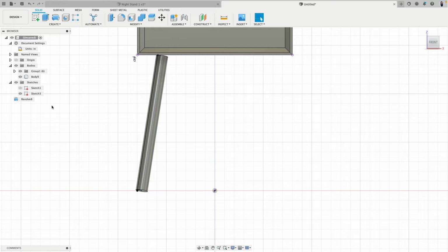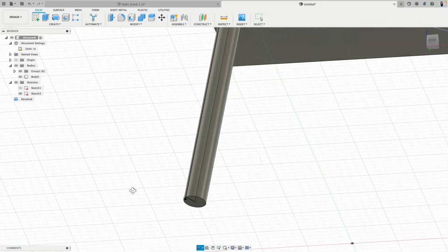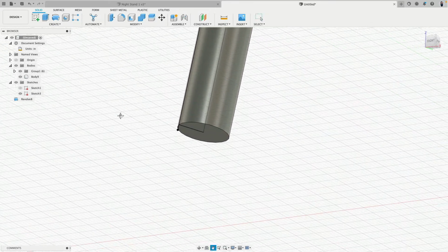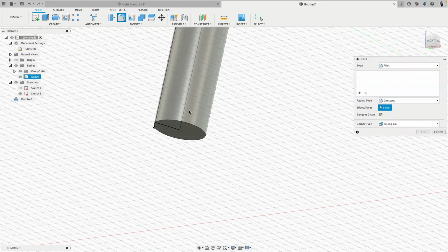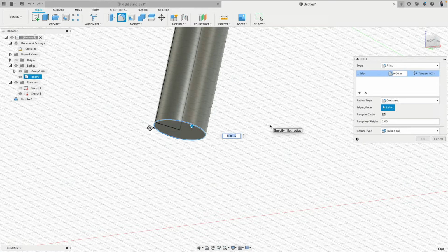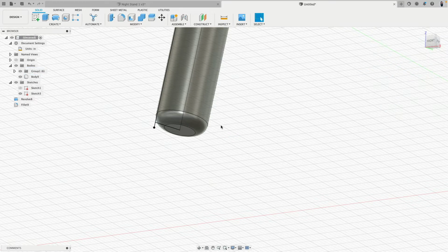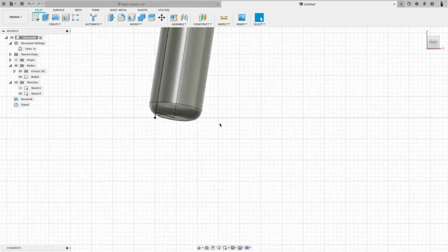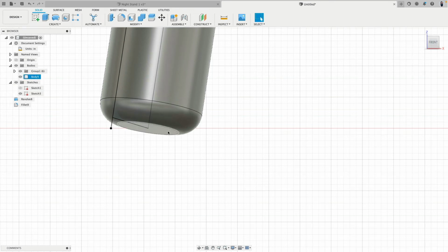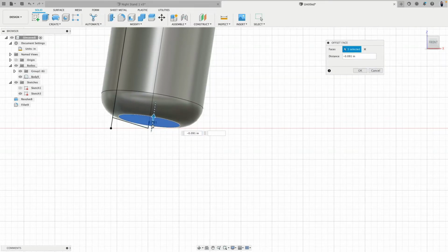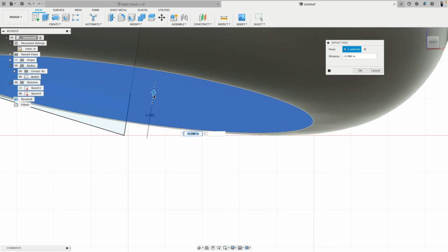It makes also sense to always work on the easiest part, and then we do the more complicated parts. So now we work on this one first. So this edge, let's see, 0.25. How does this look? Okay, that's quite nice. So we rounded this one, but obviously we can see that, well, this goes through the ground. So check this out. I go push and pull, and this face I pull up. And yeah, we're going to eyeball this a little bit. We can zoom in a tick there.